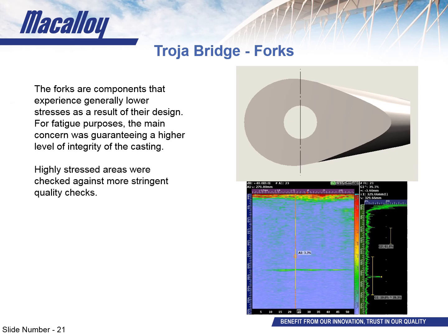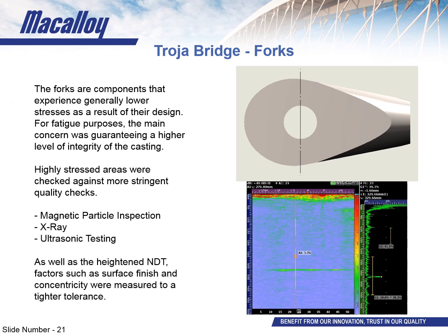In order to accomplish this, the most highly stressed areas on the component were checked with an additional source of NDT. Now, this comprised of magnetic particle inspection, X-ray, and ultrasonic testing. Then, to round off the integrity checks, we also ensured that the surface finish was to a sufficiently smooth profile so that it didn't encourage any sort of crack initiation, and then all the connection points, such as the pinhole and the thread, were concentric with where they should be.